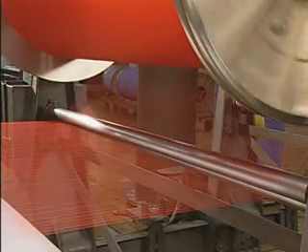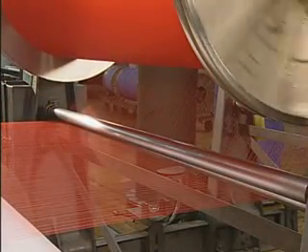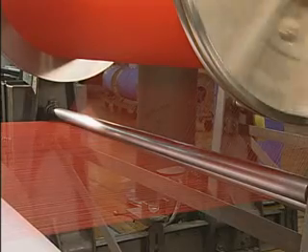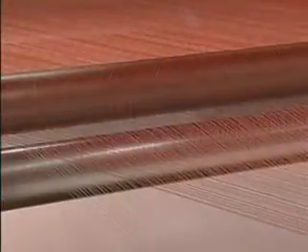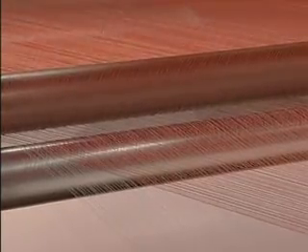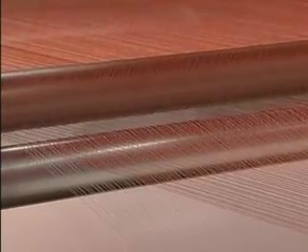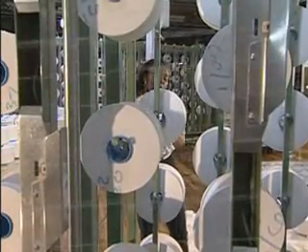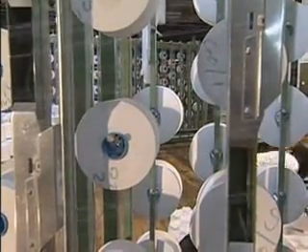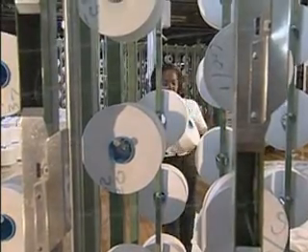For example, if the warp beam needs 3,200 ends and the creel holds only 400 ends, then a section beam will be made on the warper. Therefore, 8 section beams would have to be made to accumulate the needed 3,200 ends. Yarn packages are first placed in a creel, from which they are wound onto a section beam or die beam.